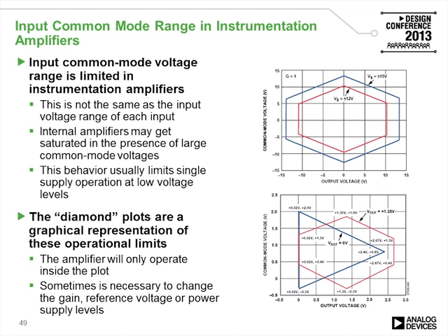An important parameter for instrumentation amplifiers is their input common mode range. The input common mode range indicates what is the valid input common mode voltage accepted for a given differential voltage. In other words, as we can see on the plots on the right, the amplifier needs to be inside of that plot in order to operate properly. The contour determines the valid region of operation.